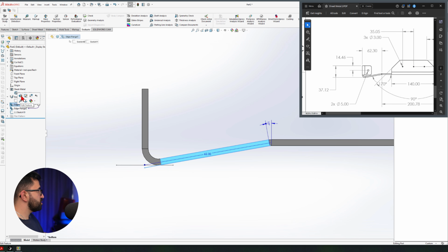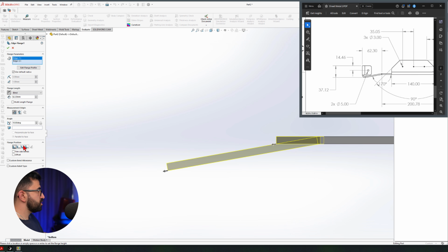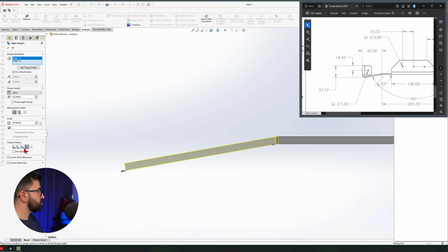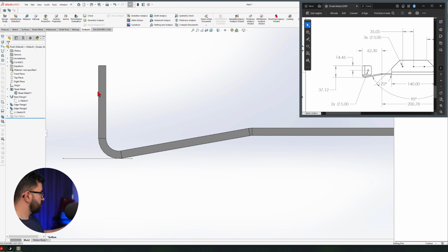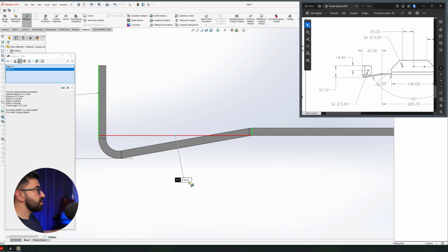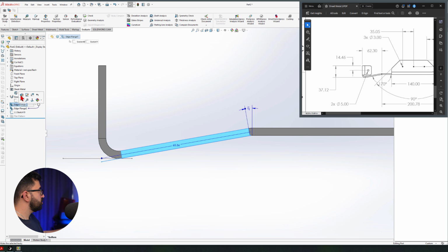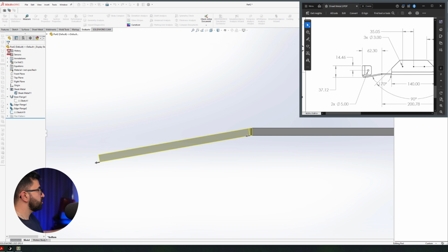And this means this one. 6230. Half of wall thickness, and this is with an offset, not this much. So I'm going to have it on the inside, just minus 1.74, I believe. One more time, measure it from this line to this line, 6130. Now 1 millimeter too short. Oh, it was just 0.74, not 1.74.